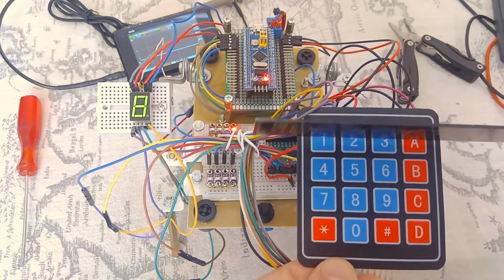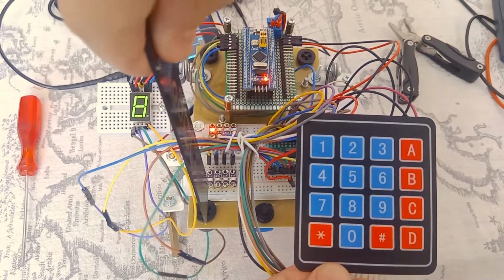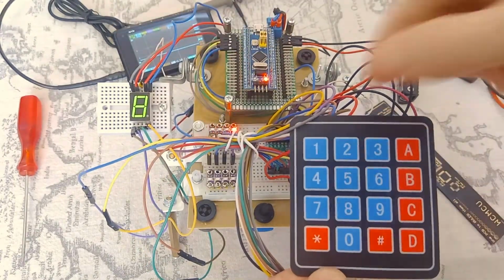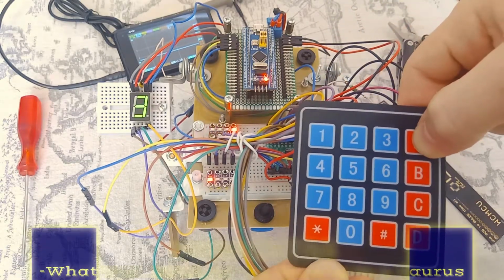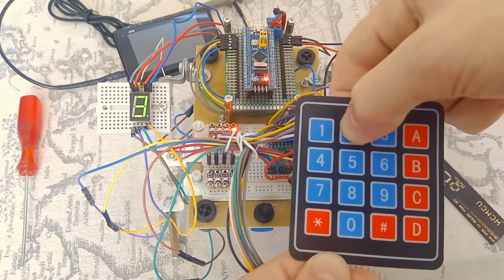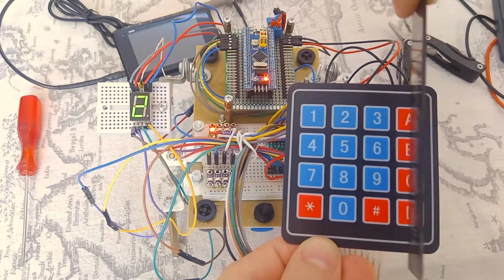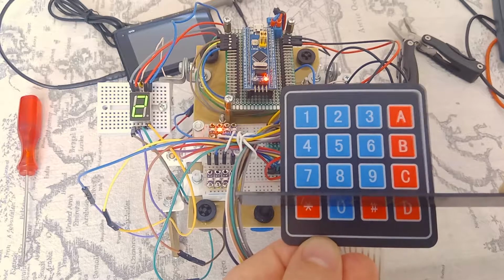We have horizontal lines, each of which corresponds to these LEDs. Line 0 is LED 0, and when you press any button from this line, LED 0 will light up. Thus, the upper LEDs are indicators of the supply lines, which are vertical, where they take turns. The horizontal lines are reading lines.